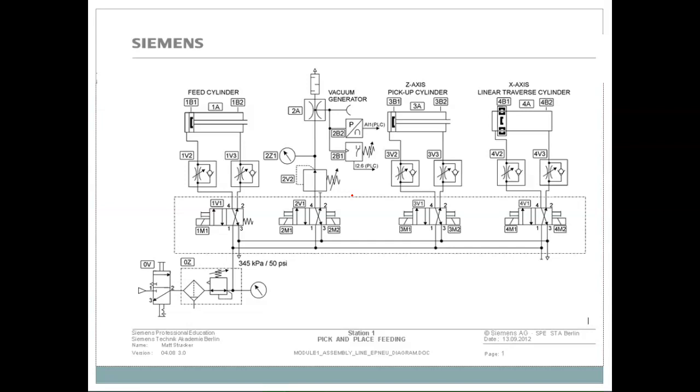For these three right here, you're looking at two-position, four-way, push button controlled valves. These all actually have solenoid control as well. You have a spring return on this one. And that would describe those valves. And again, this would all be part of one unit.